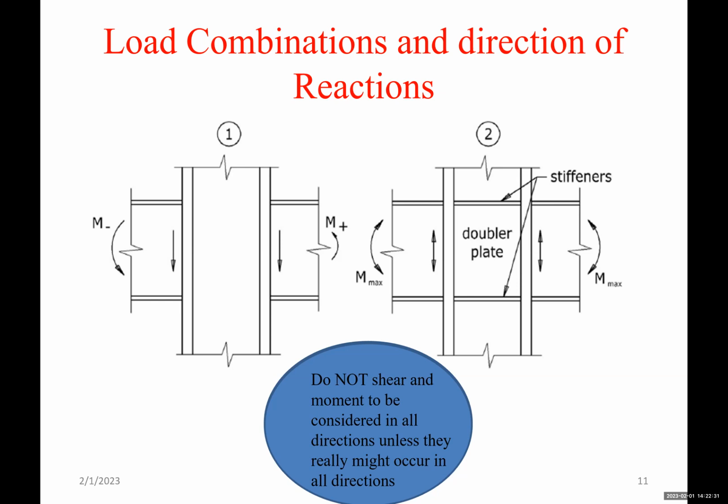If it's, let's say, a wind load, or if it's a seismic load, the moment changes. Okay, the direction of the moment changes depending on the direction of the load. So for each case, show what you have. Does the moment change direction on this connection, or is it in one direction only, maybe because it's a cantilever and it's due to the load? So show that.